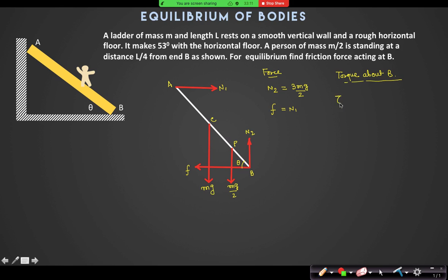So I can say torque about B is equal to 0. That will give me, what is the torque of N1? N1 sin theta into L by 2? No, N1 sin theta into L. Sorry, L sin theta into N1. Yes, N1 L sin theta.